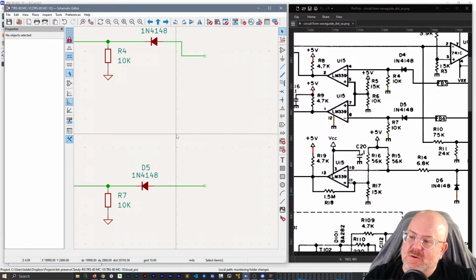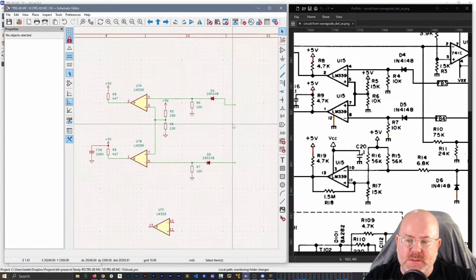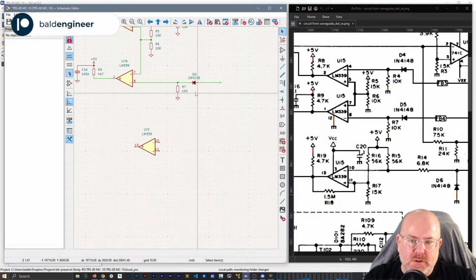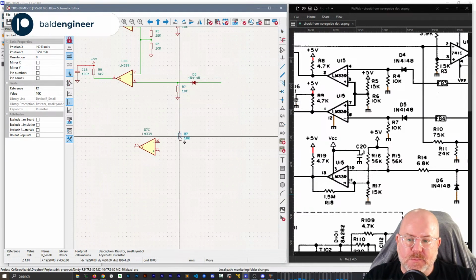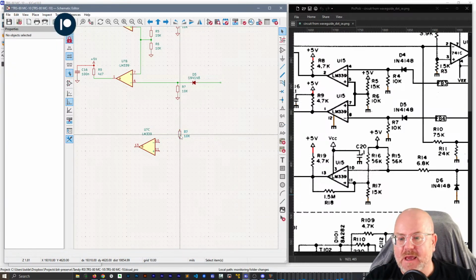The code size is on the order of a few kilobytes, and RAM can be configured to be as low as a few hundred bytes. Yeah, well. What's really frustrating is the actual problem I'm running into: the stack and the SDK require WPA, and WPA requires at least 130K of heap.